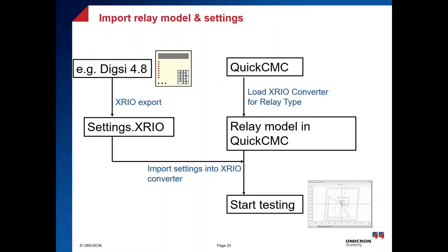Now, here we will see how we can import the relay settings, and this will be in our practical session. No need to go for the relay characteristics. Now, what we will do is talk about the customized PTT first and how it will save your time. Just click, and then you will get all results in the PTT in the test report.